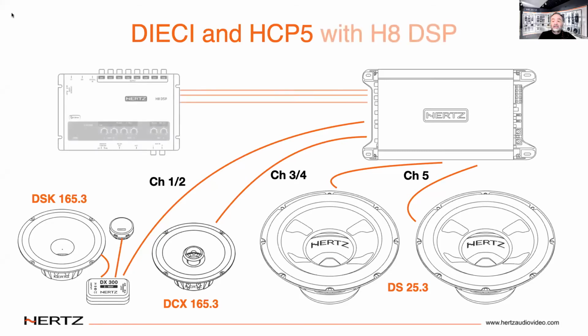Yes, it is. Now, if we add an H8 DSP to this, we can manage the overall system response much better. We can keep the rear speakers from interfering with the front speakers using delay, and that would eliminate cancellations from that. We can keep subwoofers from interfering with the cabin midwoofers at the crossover point, and we can use advanced, steeper crossover filters to get better power handling.